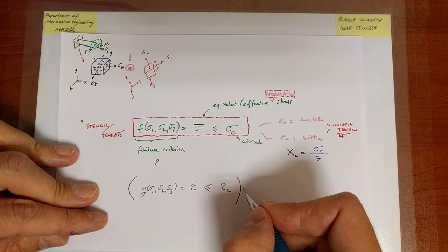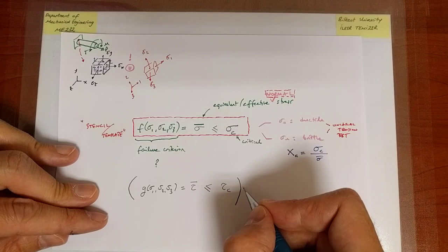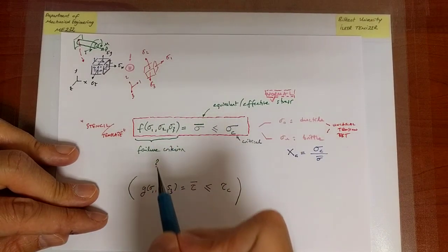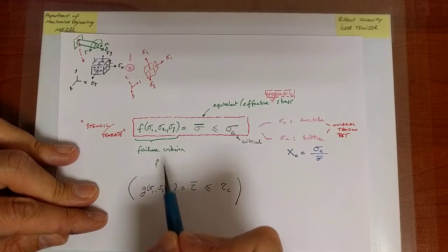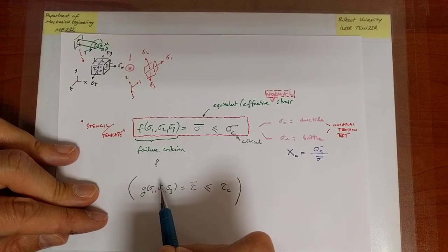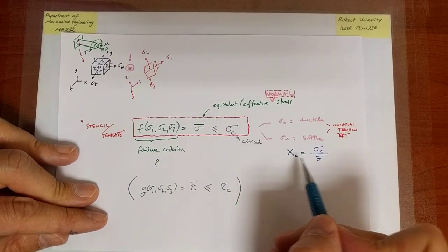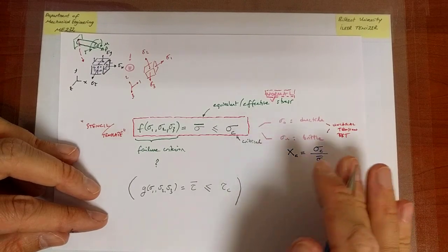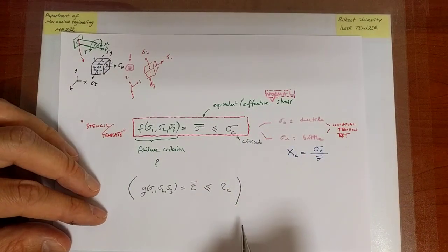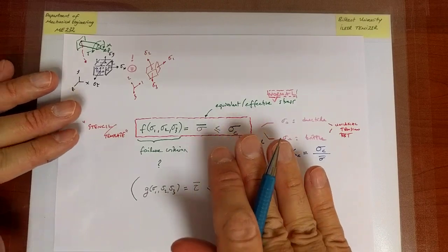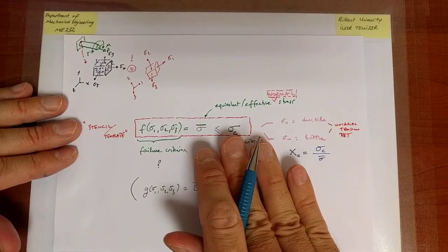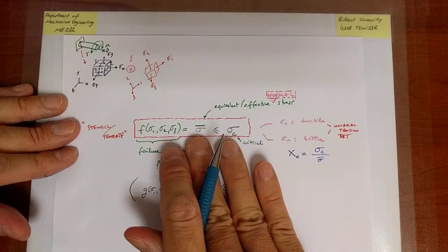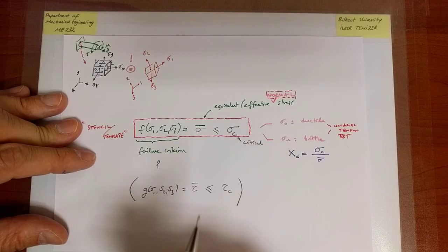And you may want to come back to this remark as well: the safety factor for a given state of stress, irrespective of the form of the criteria that you are using, will always be the same. So that will not change. All right, so back to our stencil. I had two remarks. The first one is that I'm formulating everything through an effective or equivalent normal stress.